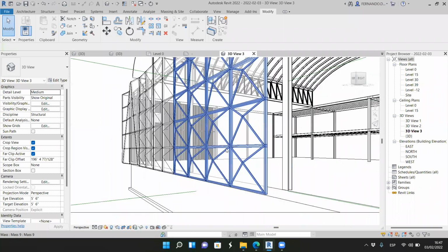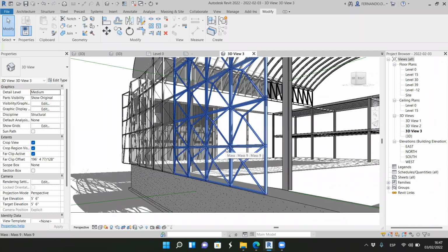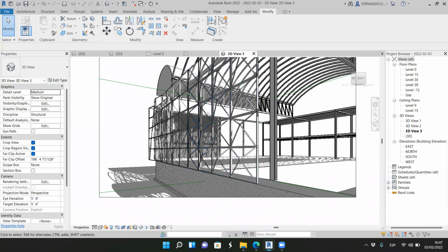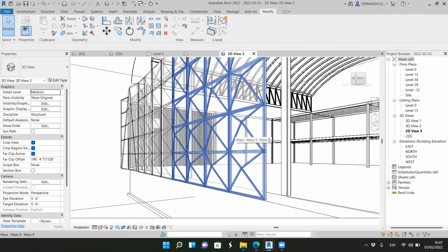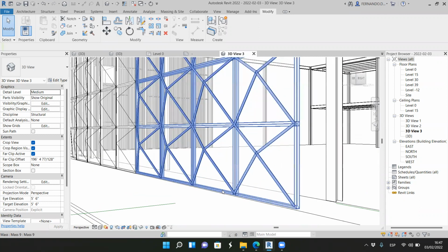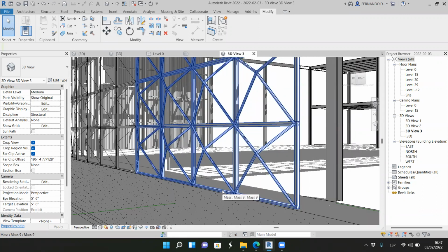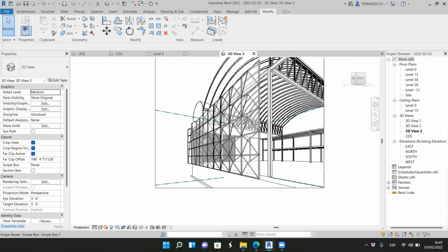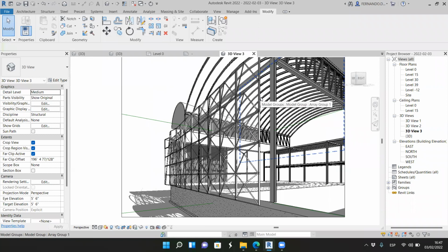That's an interesting way to design things, because basically we are just working with modules and then we are changing the module. So this is an introduction to parametric design. In parametric design, we can adapt a module to different shapes. We have to create a mass, so the mass can have any shape. We have already created our own module as a family, and then we adapt this family to the mass we're working with. I think this is more than enough for today.